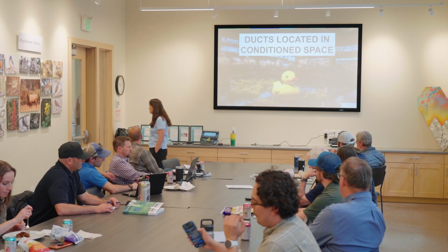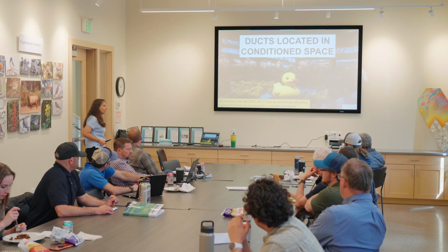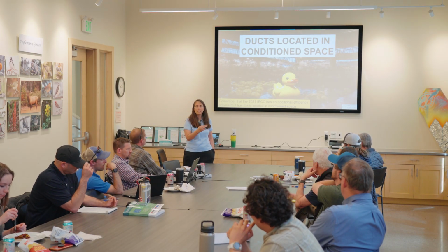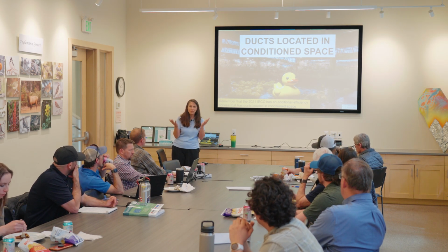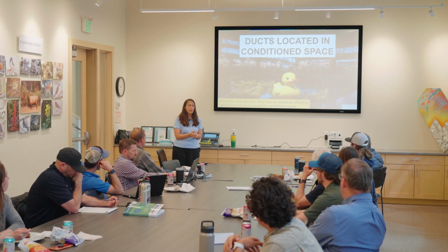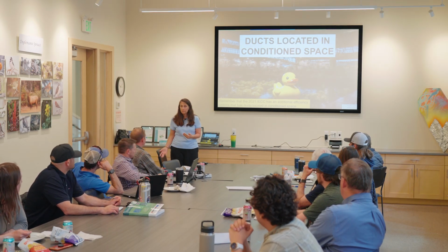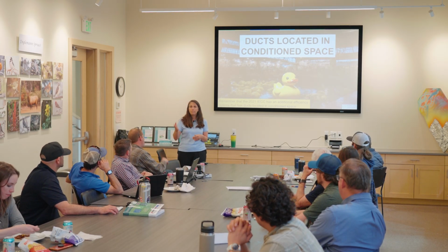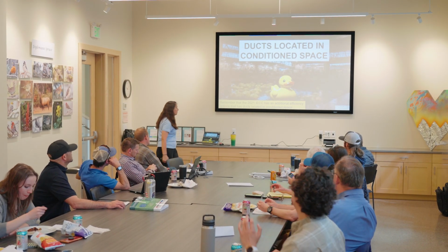Now, this is going to be important because later on, and I don't know if I put it in this class or not, but remember that the 2021, both on the commercial side and the residential side, but more importantly, the residential side has this new thing that came in that talks about additional efficiency options. And so you have to pick one of the options if you go prescriptive or performance. The only one that doesn't have to do it is the ERI path, but as we talked about, they have to reduce their number compared to what's on the table.